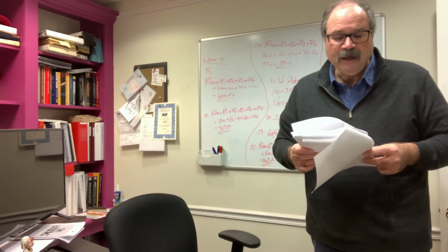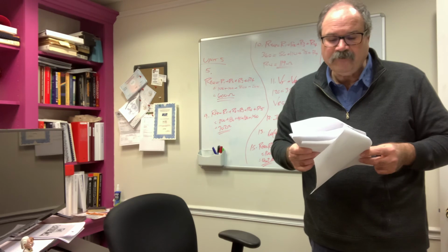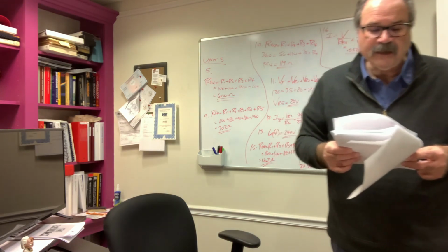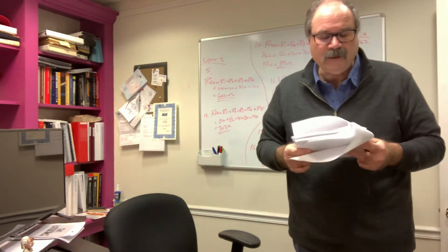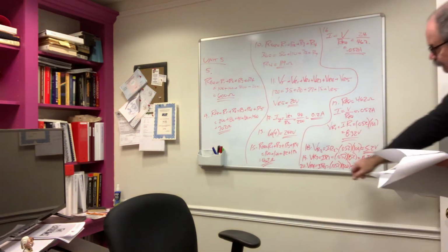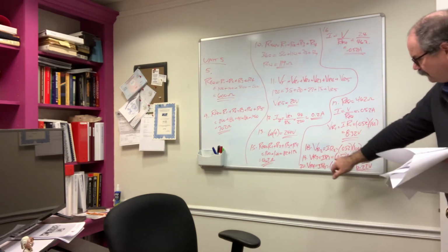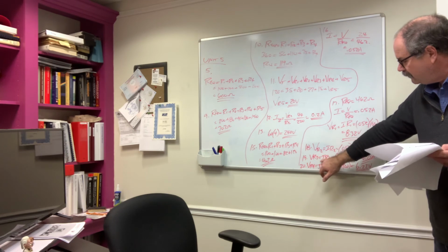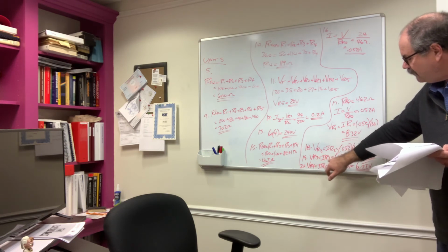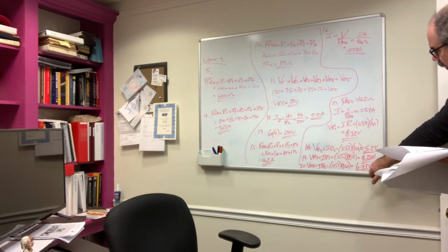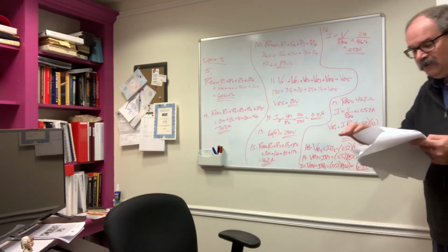Question 19. A series circuit, again, same value of 4 resistors, 160, 100, 82, and 120 ohms, connected to a 24 volt power supply. This time, what's the value of voltage dropped across R3? Simply plug the numbers in again, same expression. Voltage drop across R3 is the current times the value of that resistor, R3. Plug the numbers in, and I get a voltage drop of 4.26 volts.